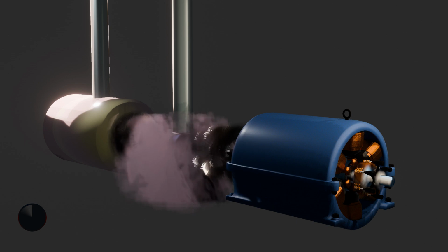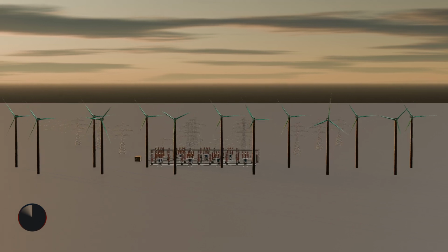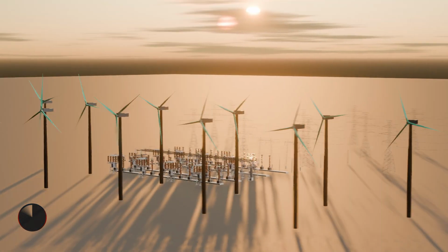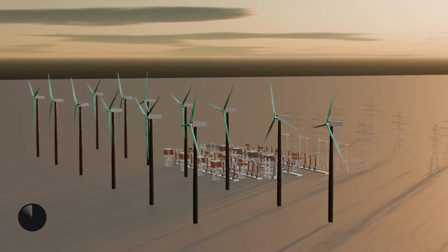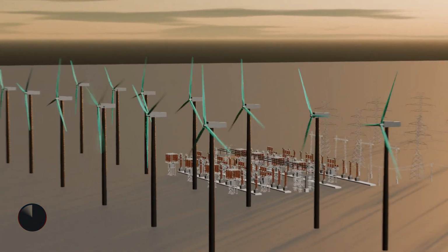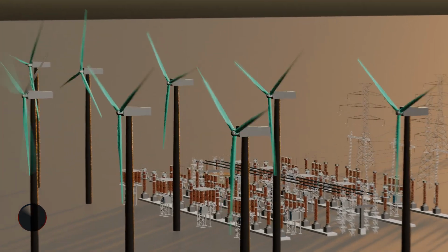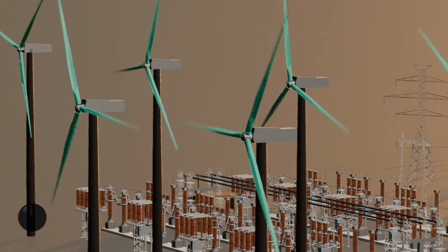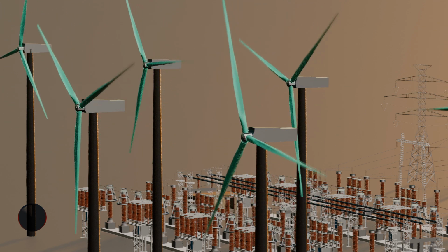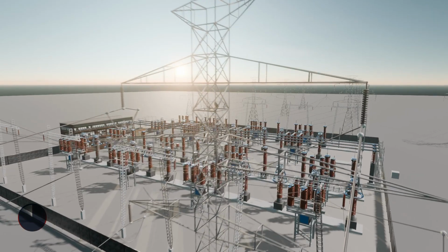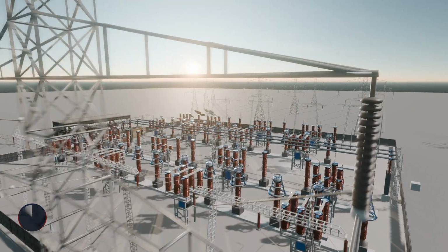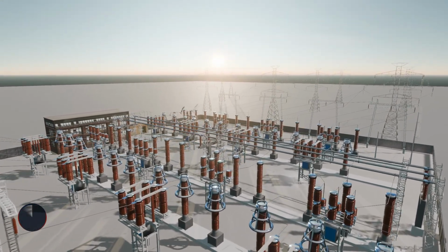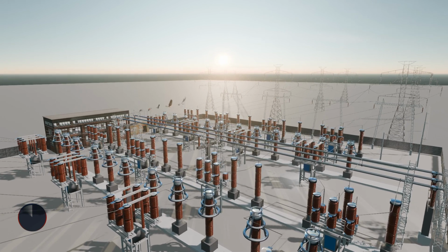The diversity factor of the grid can be improved through the use of diversified energy sources and load distribution. That is, by incorporating a mix of renewable energy sources such as solar and wind, which limit the dependence on a single source of energy, it improves the diversity factor of the grid. The third point is that it reduces plant reserve capacity since several power stations are interconnected in parallel, and the reserve capacity of the system is reduced, thereby increasing the efficiency of the grid.